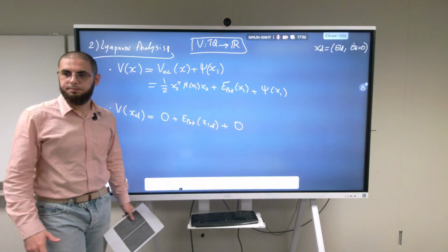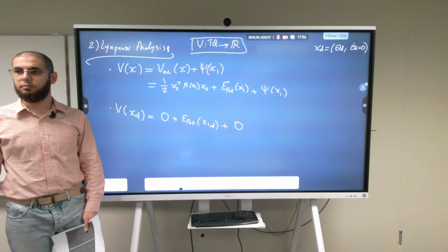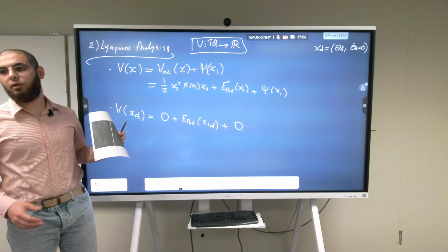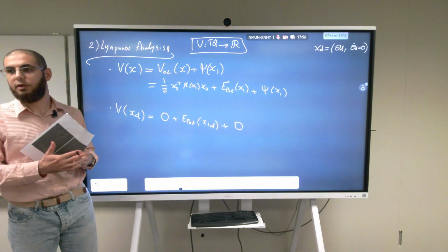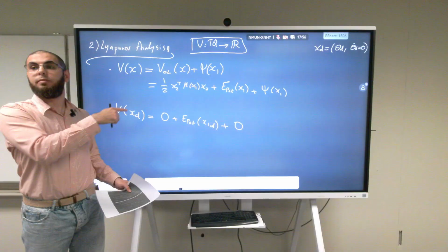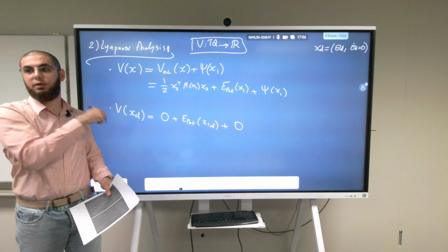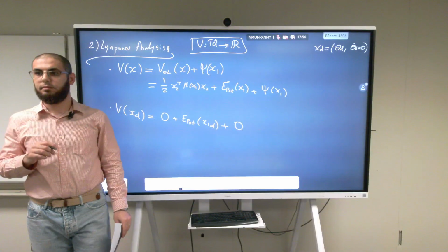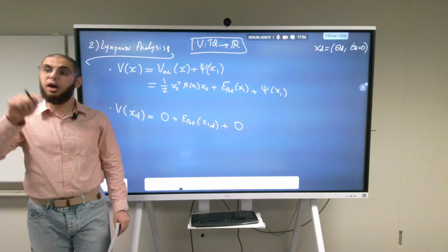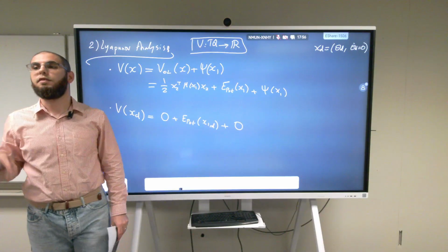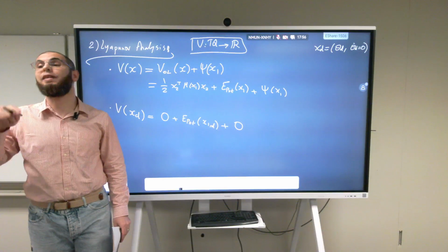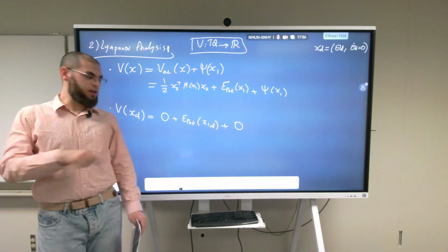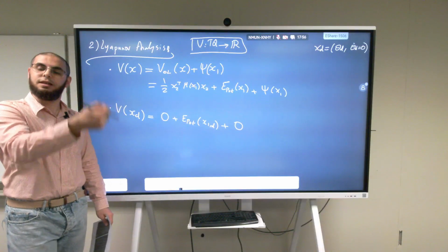For the positive definite Lyapunov function, should be only at x equals 0 to be V equals 0, right? It should be at the x star that you want, whatever equilibrium point you want the system to have. So we want the equilibrium point of the closed loop system to be x desired. This is our desired equilibrium point, the one on top. But I know for the Lyapunov function, it should be V of x star equal to 0, not V of 0 equal to 0. V of the x star, the one that you want, that is an equilibrium point of the system.